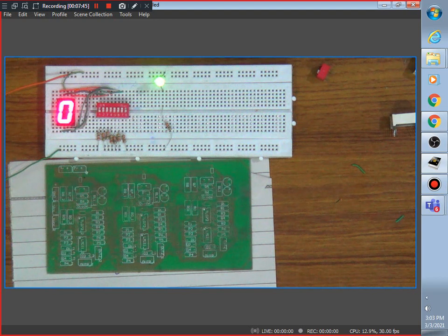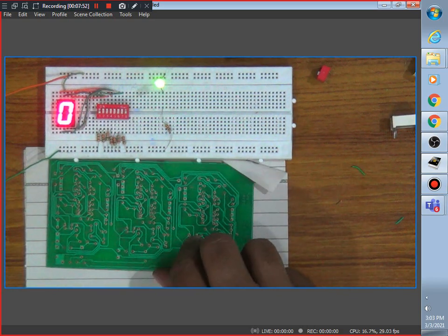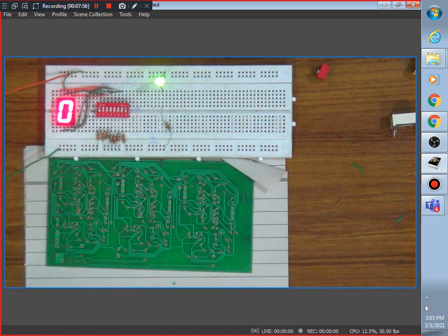For wires, you don't need any footprint. Why? Because they are actually going to be made up of copper, just like this PCB over here. And on this PCB, as you can see, the coppers are sketched on this printed circuit board or the fiberglass or bakelite sheet. We'll talk about that later, but just for now we need footprints, and for footprints you need libraries. Now, since you are just beginners in this Altium software, you will be requiring libraries, and I will share libraries with you as this lecture goes on today.